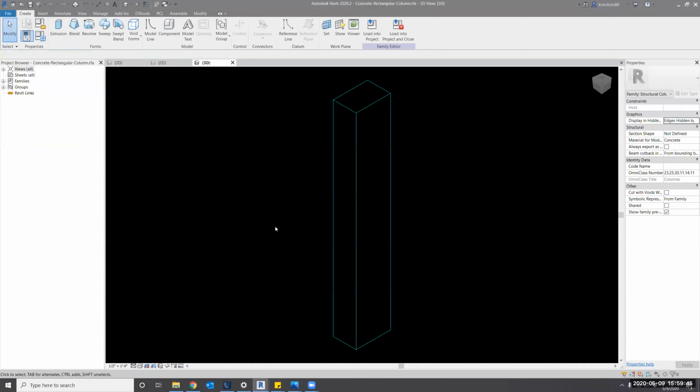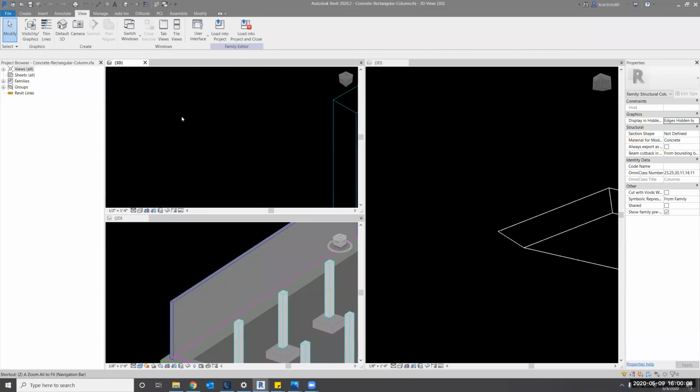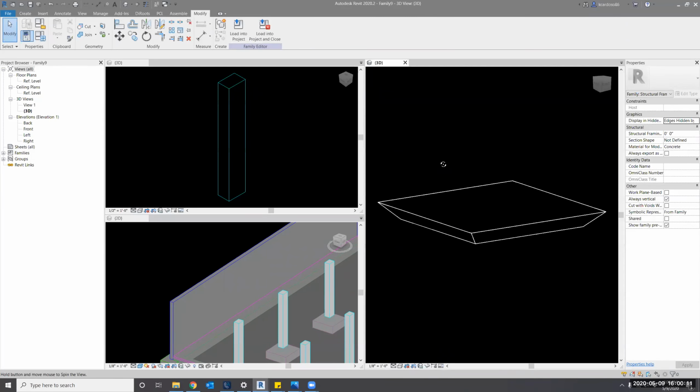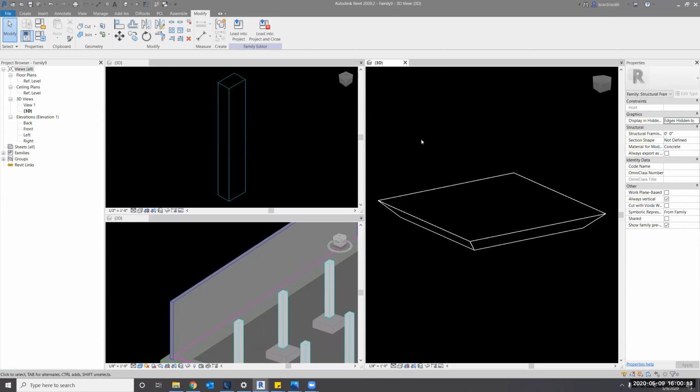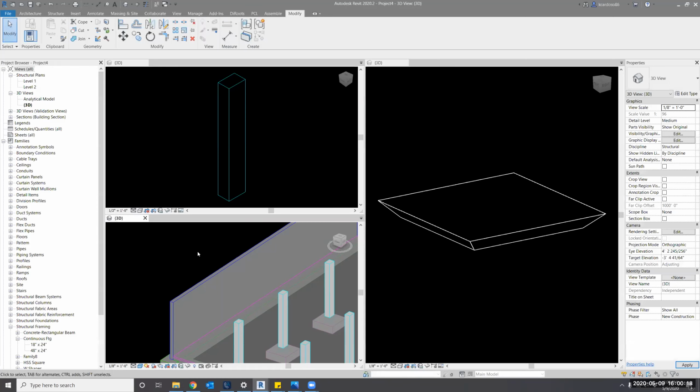Once these three files are open, you see that I only have 3 tabs open. Maybe some of you have more tabs open. Go to View tab, and this guy, Close Inactive Windows. Okay, you should at that point just have 3. Once you have just those views open, hit Window Tile on your keyboard, WT, and do a zoom extents on the 2 elements that we're working with. So this thickening is going into this family that's going into this project.